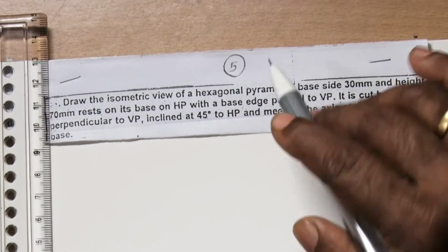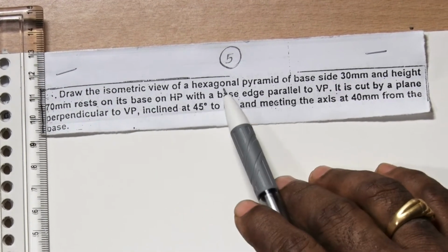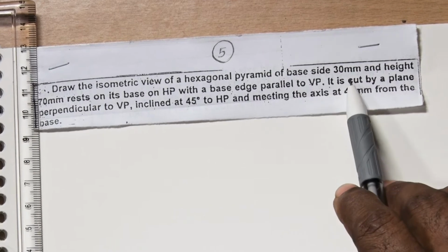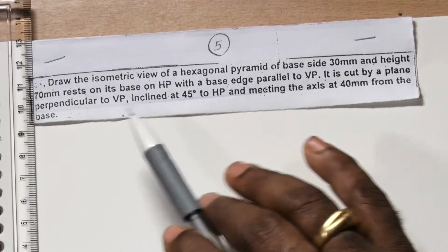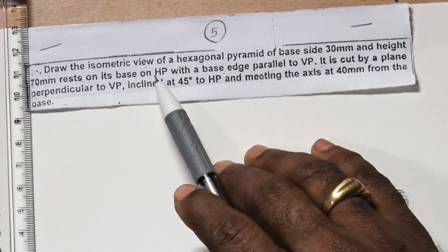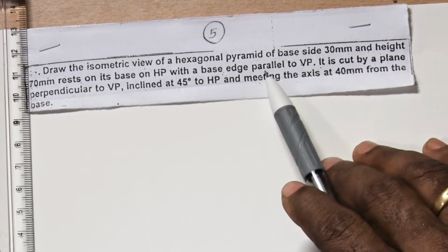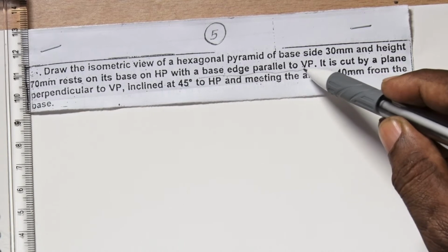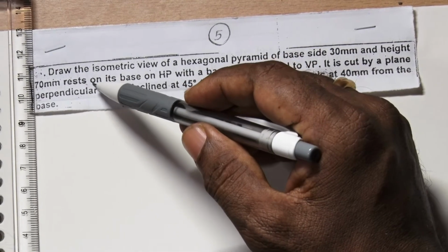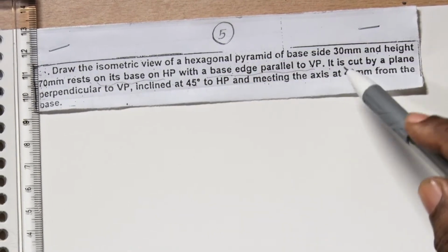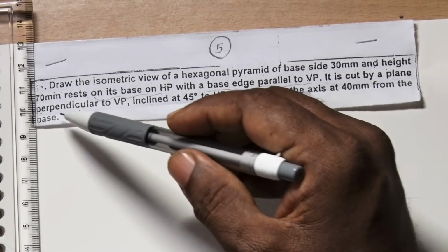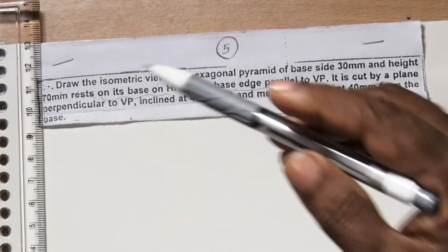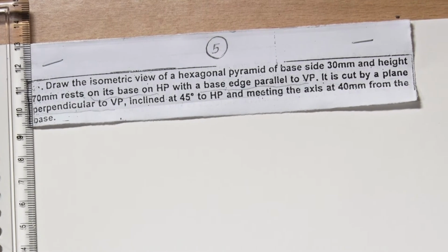Problem number 5. Draw the isometric view of a hexagonal pyramid of base side 30 mm and height 70 mm, resting on its base on HP with the base edge parallel to VP. It is cut by a plane perpendicular to VP,